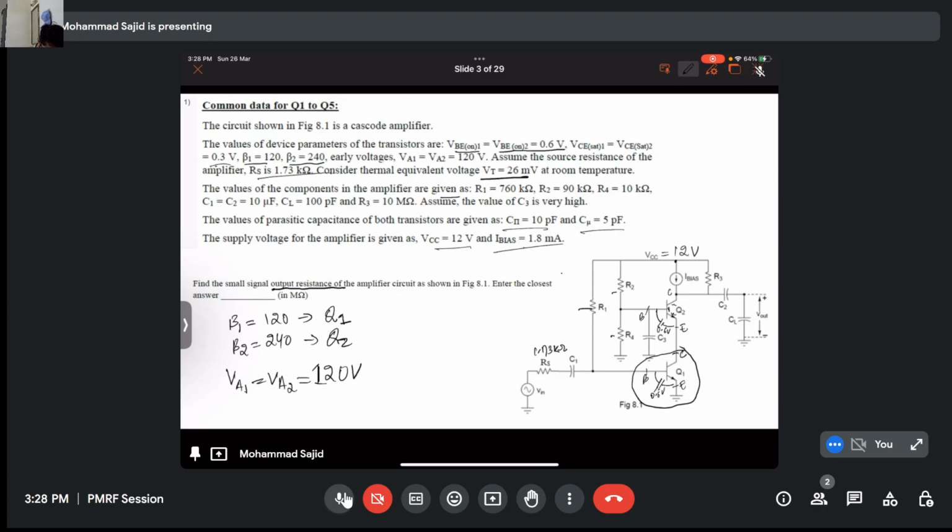Okay, so if you see the circuit, now if you want to find this base current, it's easy, right? From this point of view, it will be difficult because there are different paths. There is a path through R4 as well. But here you can see there is a capacitor, DC block. So if a current comes in this loop, all the current will flow through here. So this will be treated as a base current.